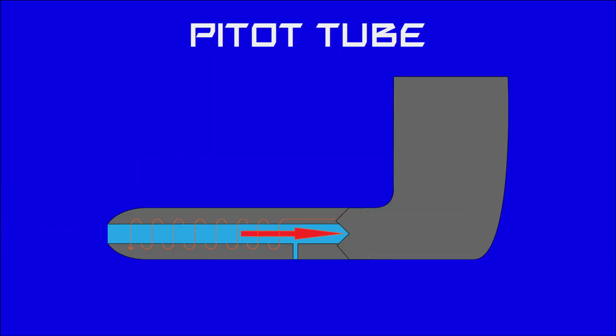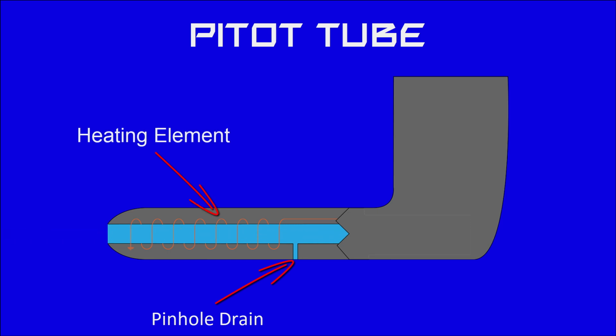The air can either be brought to rest inside the pitot tube against the stagnation wall, which is merely a pressure sensing flat surface, and then transmitted up the pitot pipeline to the user instrument, or pass directly up the pitot pipeline. A pinhole drain allows any moisture to leak away to the atmosphere without significantly affecting the sensed pressure. The probe is also equipped with a heater which is powered from the aircraft electrical supply and switched on as required by the flight deck crew to prevent the formation of ice.